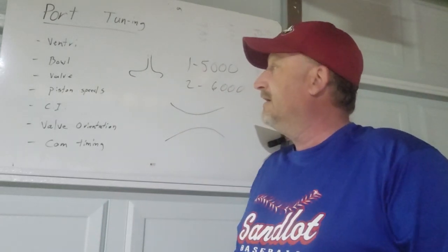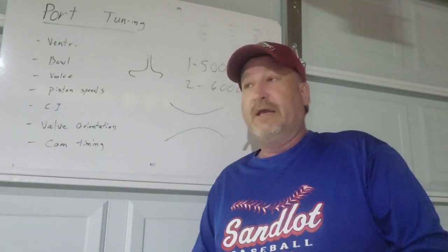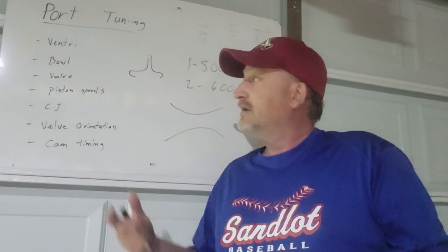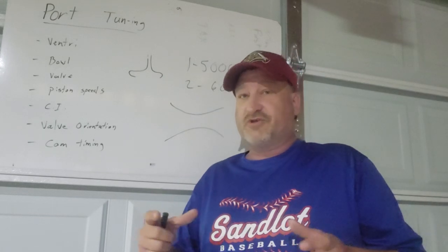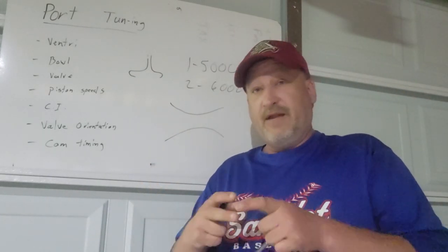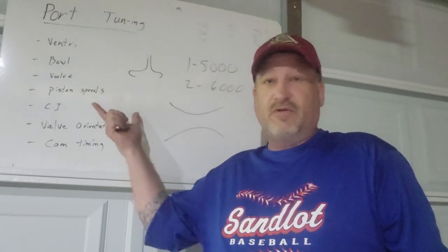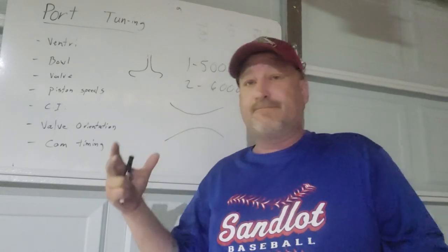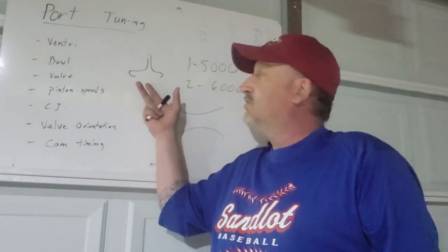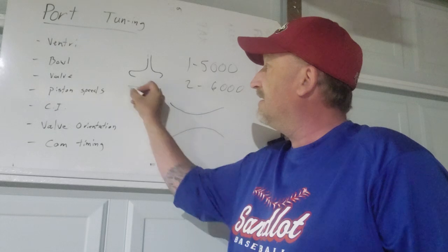Cubic inch, again, the larger the bore or the larger the stroke, will increase the amount of demand that the engine has to fill the cylinder. So a large bore, even with a short stroke, the piston speed is increased. And because of the area around the valve and the larger bore, it deshrouds the valve. So a little bit more is put onto the actual combustion chamber design to allow more of that air to transfer when the piston is near top dead center.